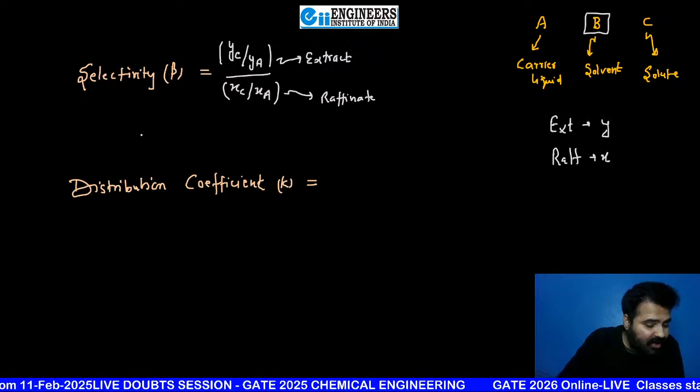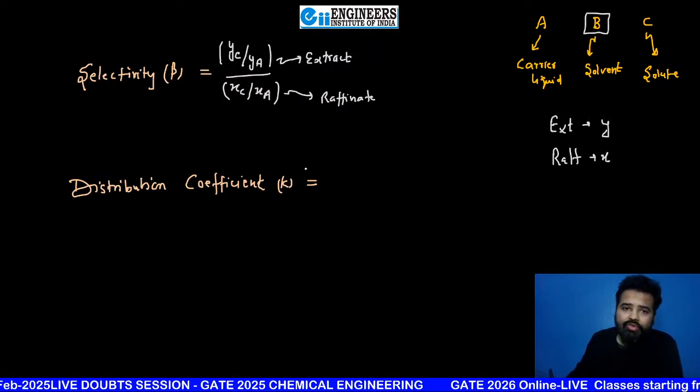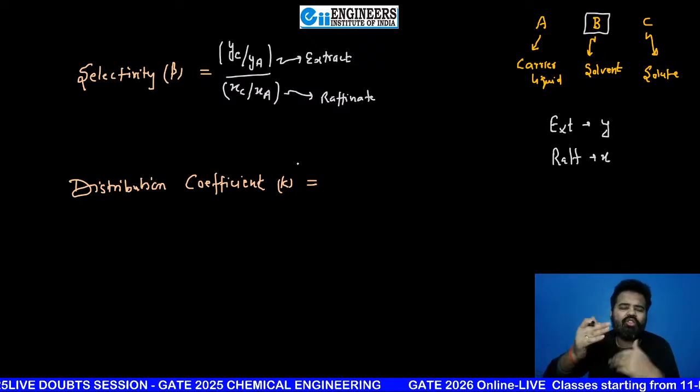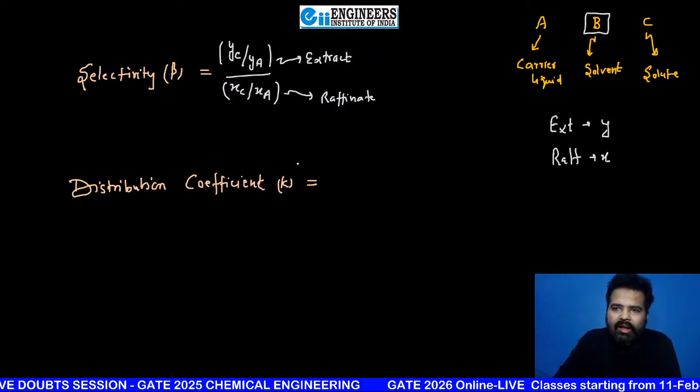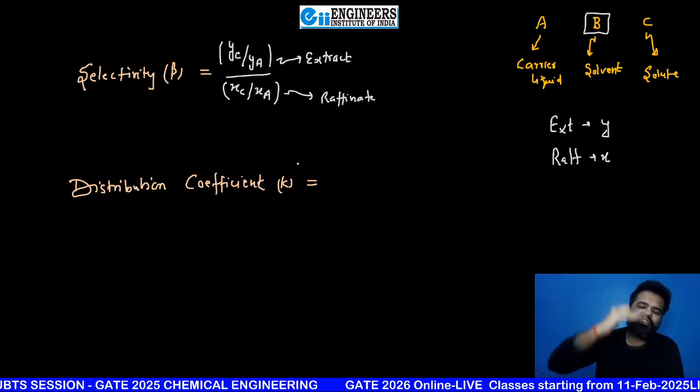Carrier, beta, solute of extract to raffinate. क्या बात बेटा, यहाँ देखो बहुत easy है. Now distribution means what, beta? Distribute. How your solute, who is distributing, beta? कौन distribute हो रहा है यहाँ mainly? Definitely solute is going to distribute between two phases, extract and raffinate.